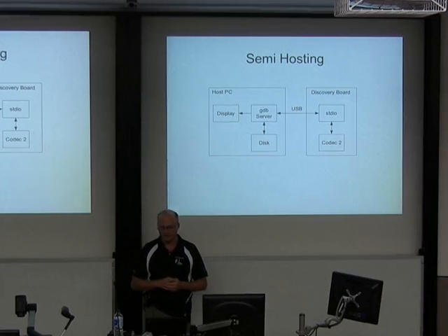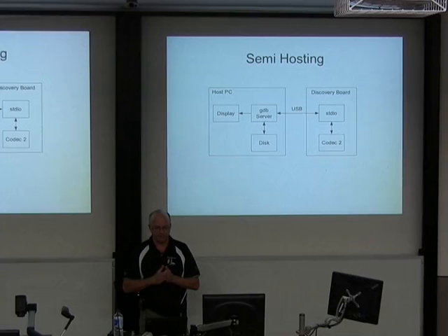This technique, I actually first did it 20 years ago for a really early DSP board, an ISA bus card sitting in an old XT PC or something, and I copied the idea from another guy. I thought of using it again, but then I figured a bunch of other guys must be doing this, and I looked it up, and it's called semi-hosting. So I found something out, but I've been doing it for 20 years and didn't know what it was called.